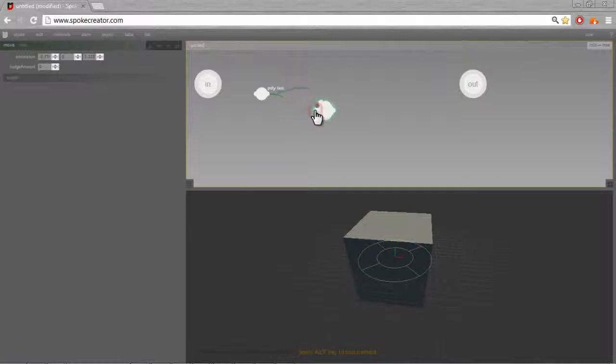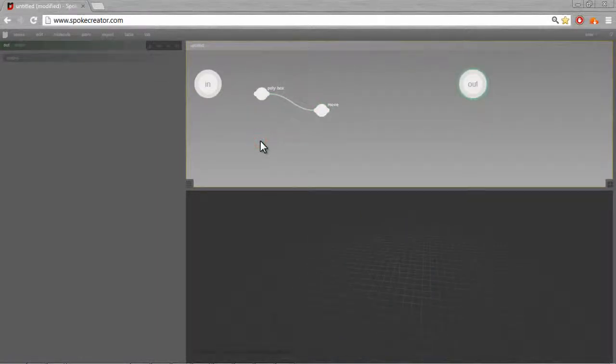So if I click on the inputs of the move here, you can see that we have two options, the nudge amount and the translation. What we're going to focus on here is the translation. That is an input that will take in a vector and move the geometry by a certain amount or direction that the vector is prompting. So let's create a really simple one. We'll cover vectors a little bit later, but just for the example's sake, I'm going to search for XYZ to vector.